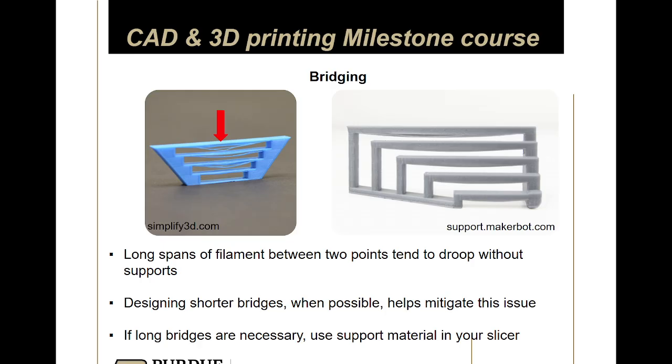So I don't want that to happen, because I want your finals to be nice and something that you can have on your desk or be a functional part for something that you might find useful. So I recommend you don't do any super long bridges. If it does require bridges, again, if you really need it, I'll add supports if it needs it. But again, it's good practice to design these limitations out of your model.